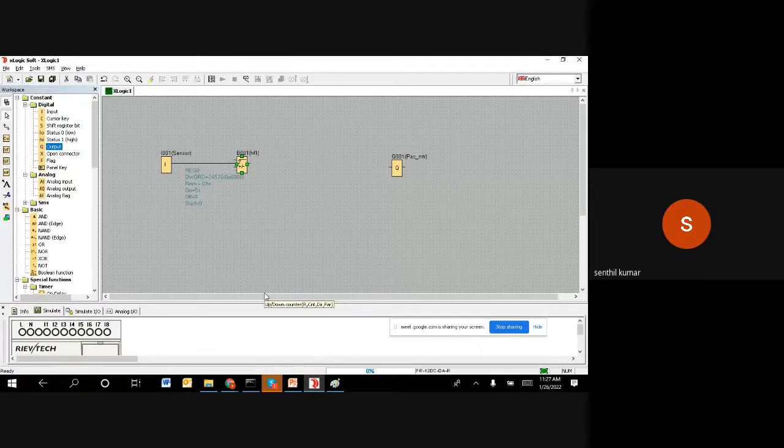After 5, I can use the counter's output directly, because once 5 bottles are produced, the counter counts 1, 2, 3, 4, 5, and then gives an output, which I can use to start the motor. But if I connect it this way, when this output is on, it will keep on continuously and won't stop further. So I want to try a slightly different mechanism.